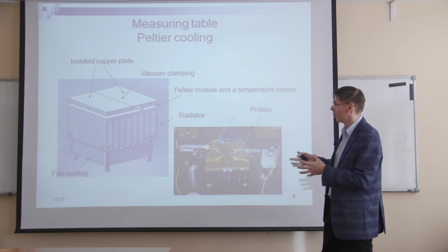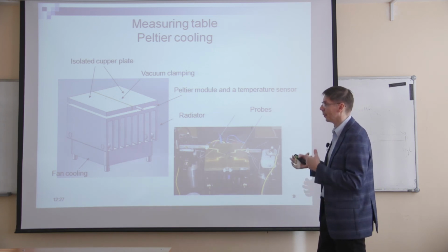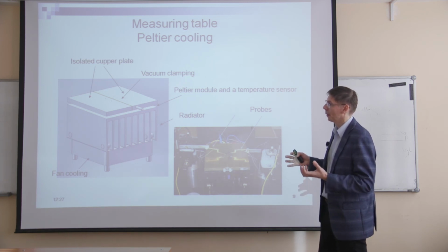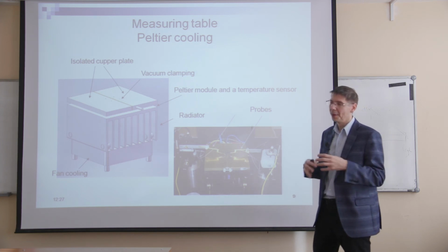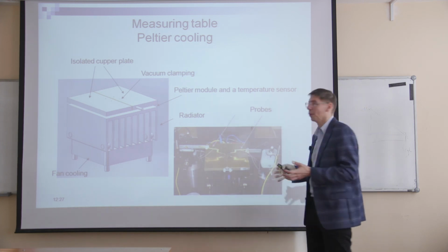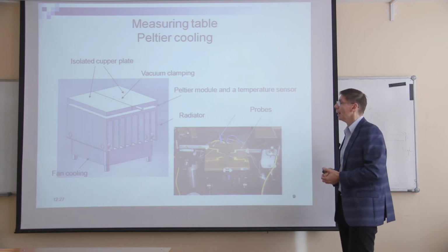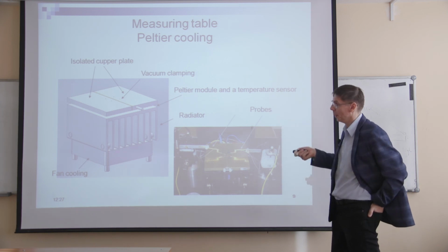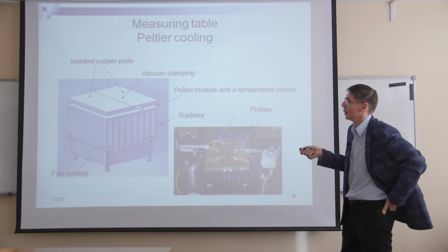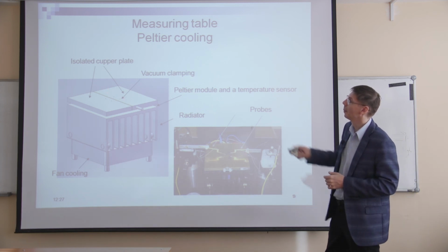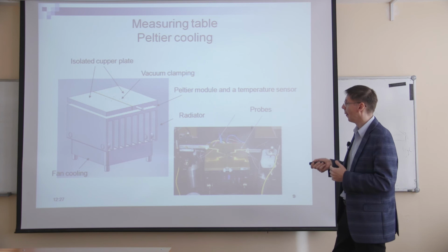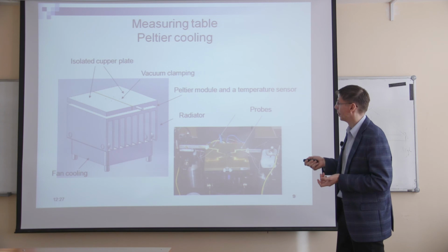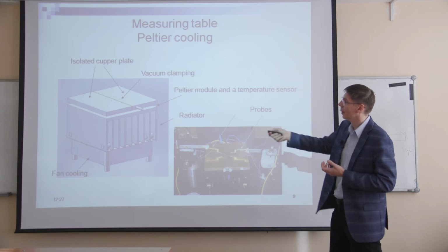And the requirement of the solar cell. But at least you can easily get some fast measurement of the temperature dependence of your solar cell parameters. So again, you can imagine some system which has vacuum clamping and provides 4-terminal measurement.